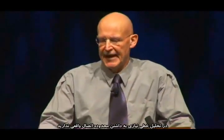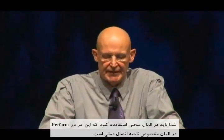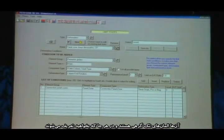Incidentally, in a linear analysis, you often don't need an actual panel zone element. You can estimate the loads on the panel zone from the forces in the beams and the columns. That's okay, but in a nonlinear analysis, the panel zone could be the weak link, and it could yield. In this case, it does. And if the panel zone yields, then you have to have a specific element that will yield. And in Perform, you have specific panel zone elements. They're single node elements, and they're very easy to specify.